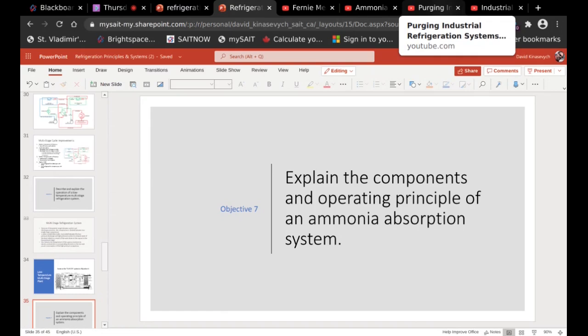The whole idea of getting rid of non-condensables from the system. Now, with a steam system, we want to get rid of non-condensables. Why? Because the non-condensables are corrosive gases. They're CO2 and O2. And so what do we do? We go to the deaerator. We mechanically deaerate it. In other words, we heat up the water, and these gases are insoluble. So if you think about it, it's kind of like a generator, where we are applying heat to water and driving off dissolved gases.